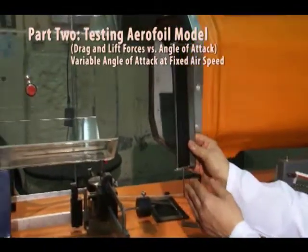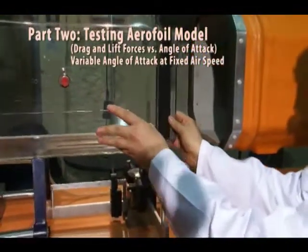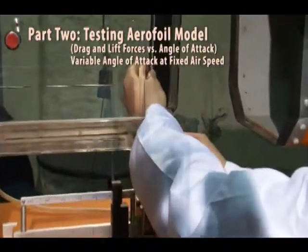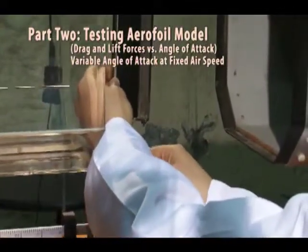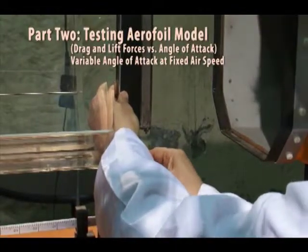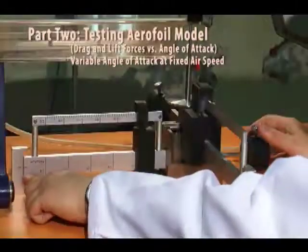Open the test section in the wind tunnel and mount the aerofoil model vertically in the lift and drag balance. Make sure that the two balance components are at the null position, as in zero force and zero angle of attack with no airflow.